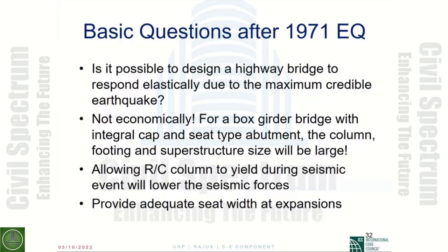So the answer is that we need to allow the reinforced concrete column to yield during the seismic event, to really lower the seismic forces and to limit them to the ultimate capacity, so that regardless of how big the earthquake is, the maximum force will be the same, right? However, for the bigger earthquake, even though you have the limit on the maximum force, the displacement will become larger.